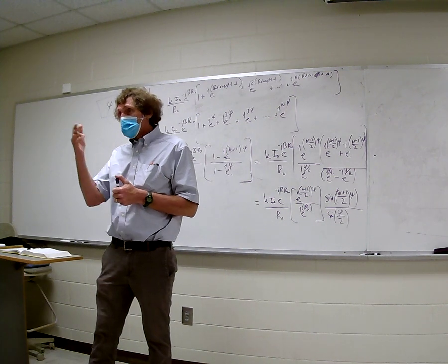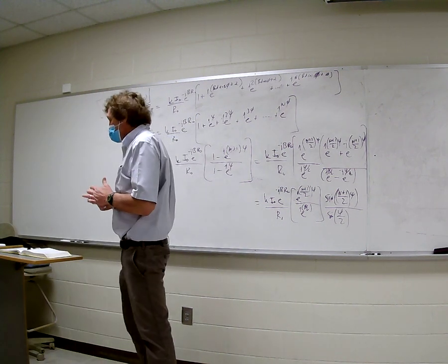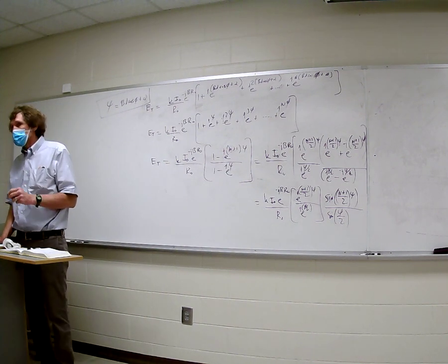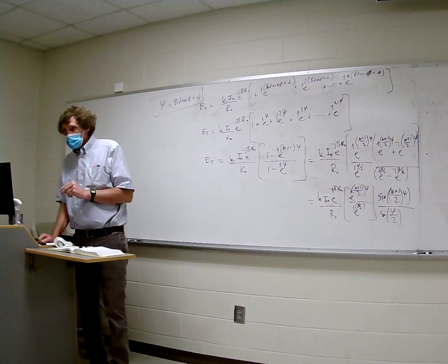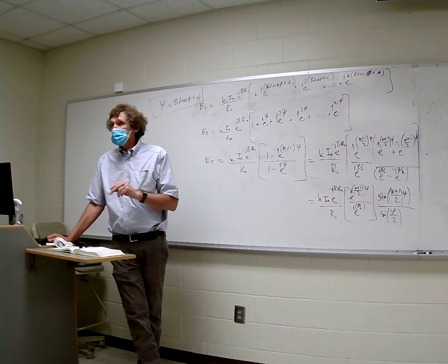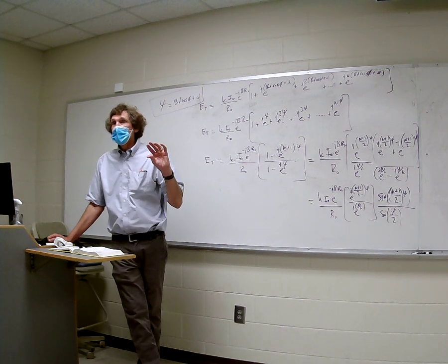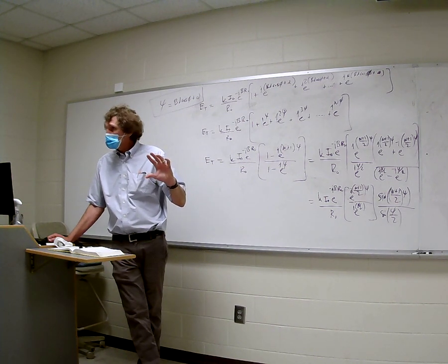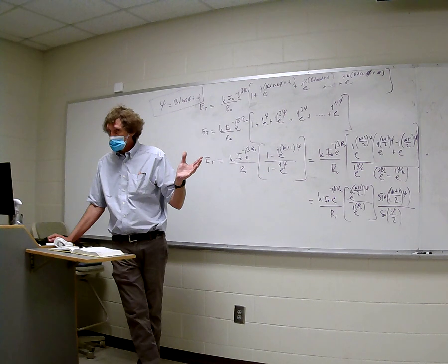I'm going to give you the bottom line on this stuff. This is called a phased array antenna, and it's used for beam steering and magnification. You're going to see the gain goes up by n squared. Remember what I just said. So if you have a gain of 100, and you have 100 antennas, it would be 100 squared, or 10 to the 4th, times 100. Do you understand that, class? 10 to the 4th is an incredible increase in gain. And this is used for extremely high gain antennas, what I'm showing. And the reason that alpha is there is for beam steering.